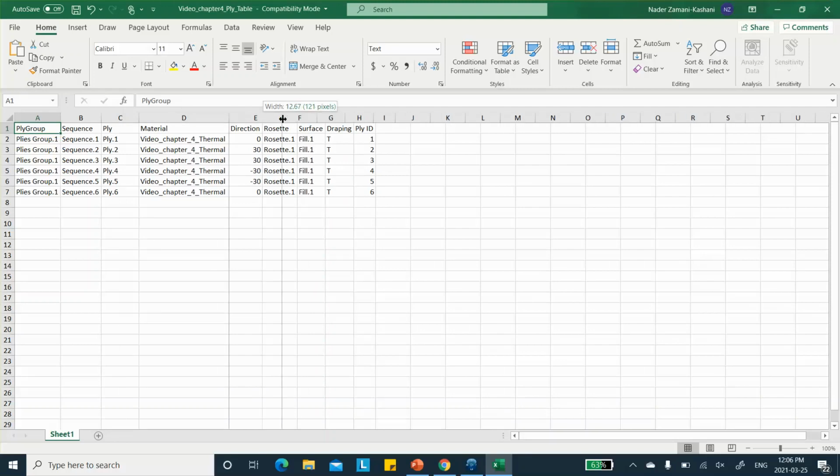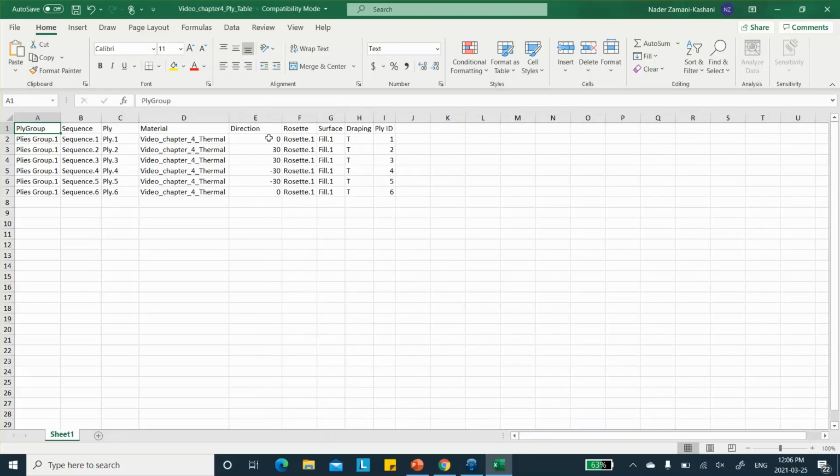And this is the orientation that I don't want. So I can change these the way I want. For example, the first one was plus 30. The next one was minus 30. The next one was 0 and 0 and minus 30 and 30. This is a lot faster and more efficient than going through the tree one by one to change the angles. There are other ways to do it too, but this is fine. So make sure you save it. So that file that I created has this information. If you want, you can save it under a different name. It really doesn't matter. We close that.